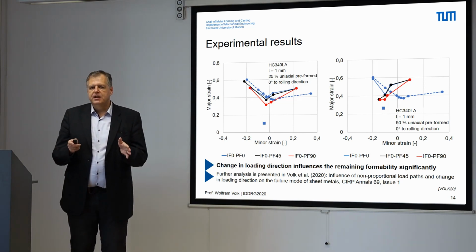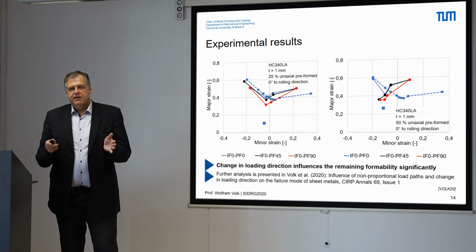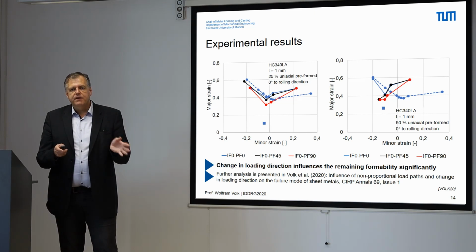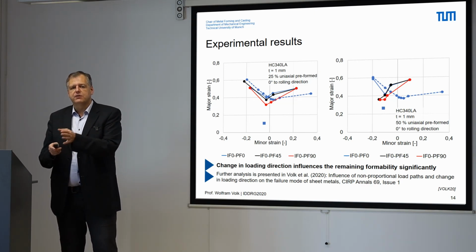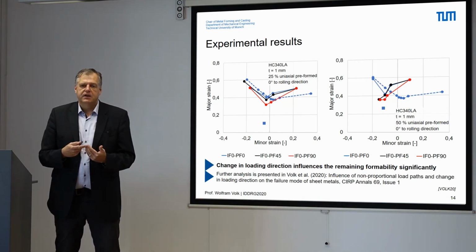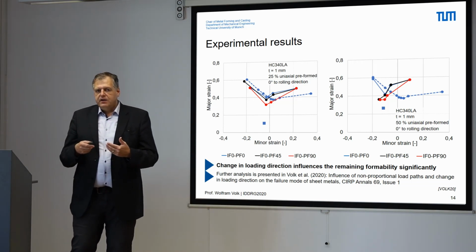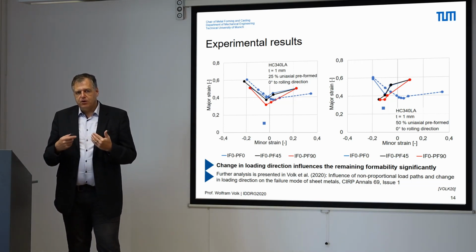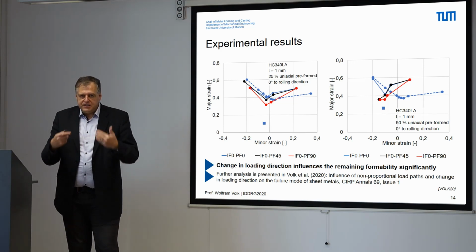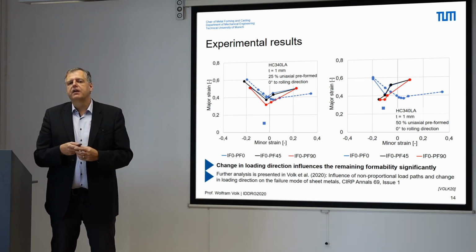Here for the IDDRG, it's important how to go on, because now we have definitely seen that this non-proportional load path with respect to different loading directions and rolling directions is a really important topic, and so far totally ignored in our industrial applications and also in the academic ones. Our important topic now is how to bring this idea into a model where we can predict within deep drawing simulation and so on.